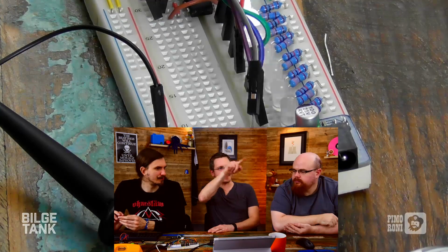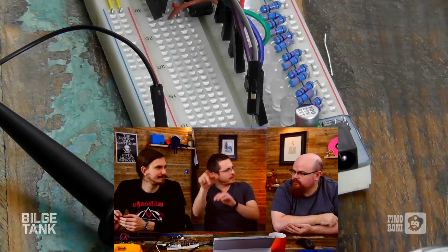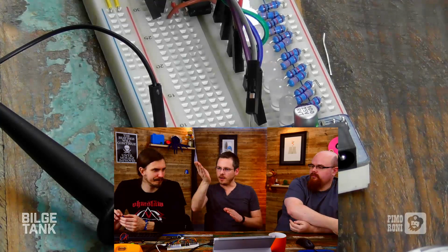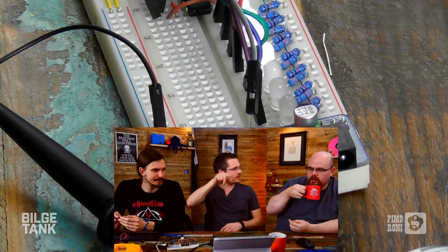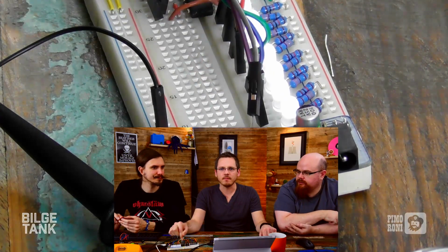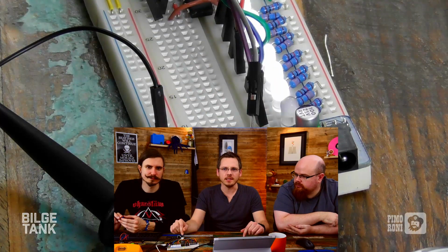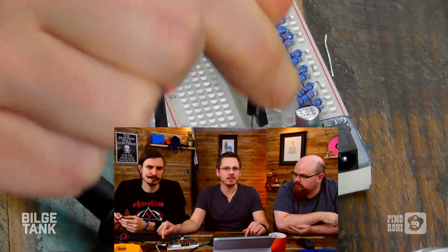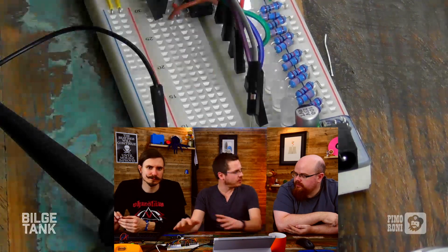Exactly that. And in this case, it's a sine wave, so it slightly flattens at the top and at the bottom. But if we made it a sawtooth, it would just be a stair step up, stair step down. Obviously, the way this information is being output is basically saying which of the incremental steps is turned on at any given moment, which isn't very useful for a digital system.